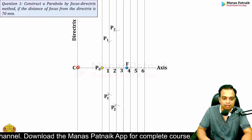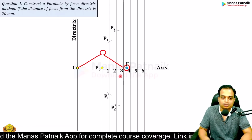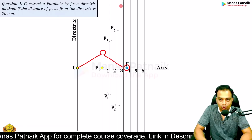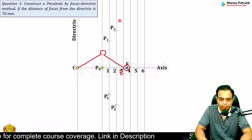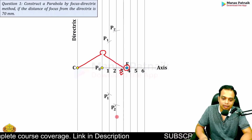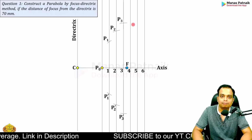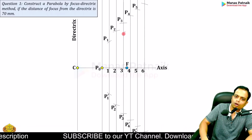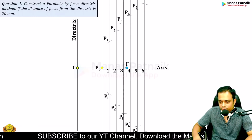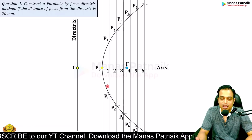In the same fashion, now with C3 as the radius, with this focus F as the center, and on this vertical line passing through 3, make a point, cut an arc above and below, P3 and P3 dash. In the same fashion, you can make the remaining points, P4, P5, P6, and when you join all of these points in proper sequence, you get a curve which is popularly known as a parabola.